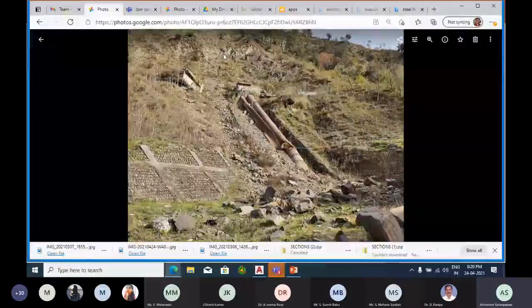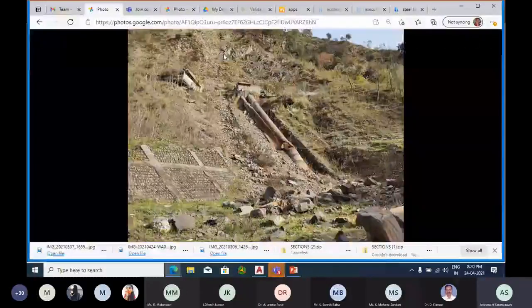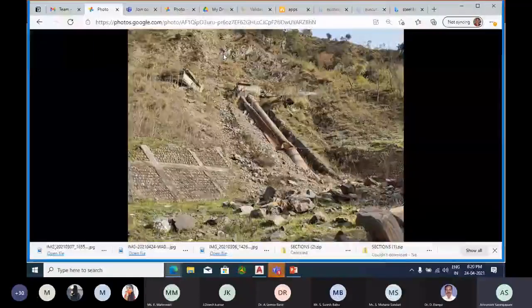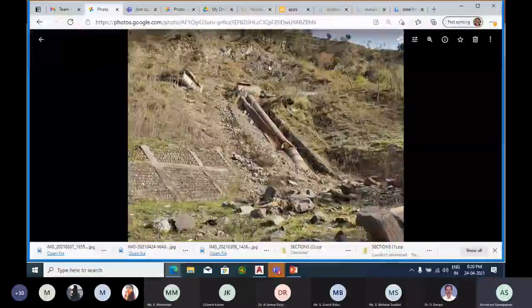Another important thing is, in the south side, if you are making a project, we will be very happy that we will have a stable slope because our rocks are granite and other things. It's very hard. But if you're doing a project in Himachal or Nepal, mostly in the Himalayan region, that's a very young mountain. Mostly this kind of slope stability failure occurs there, sir. So in a lot of projects, making the slope stable is getting costlier than laying the penstock.